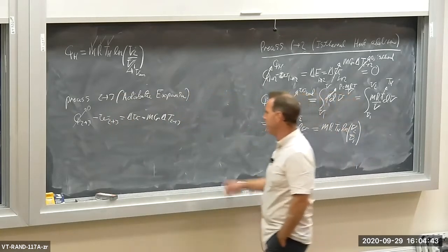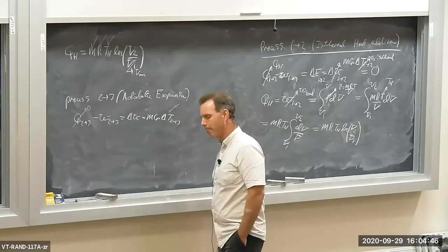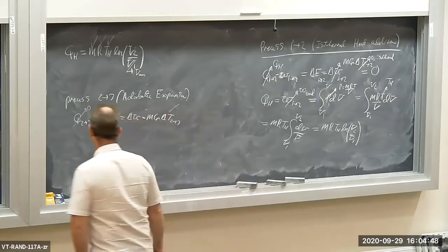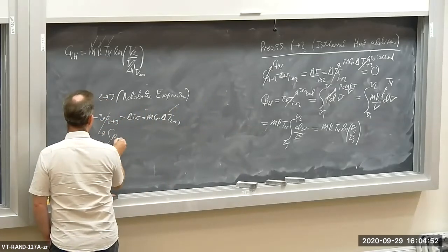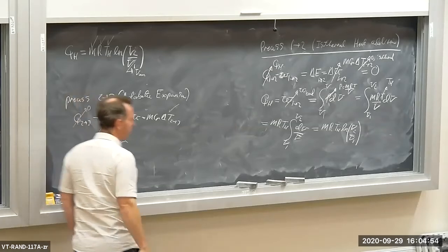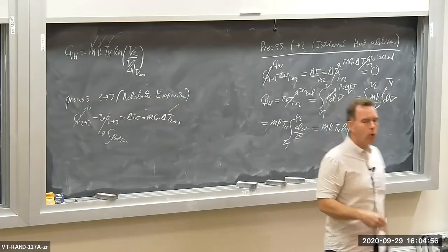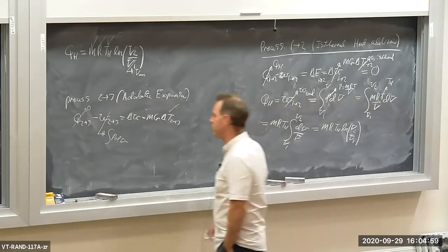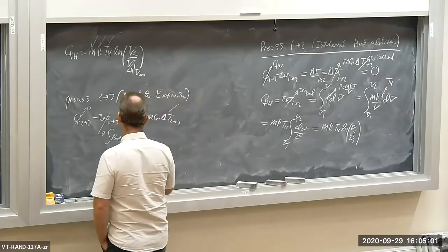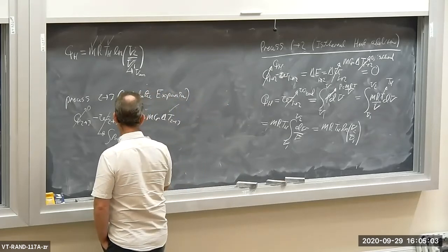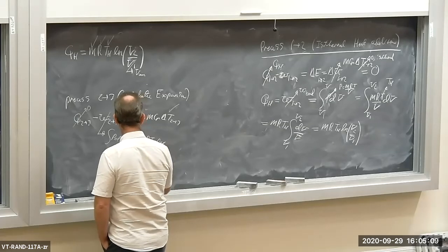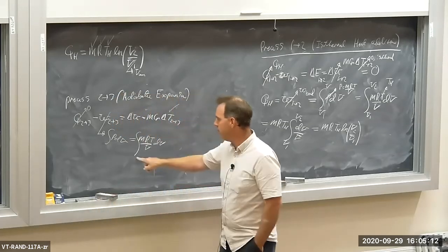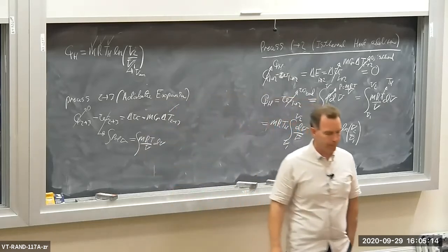I know what the temperature difference, delta T, is. And I know that the work is boundary work. So this is equal to the integral of PdV. And of course, pressure is a function of, according to the ideal gas law, a bunch of stuff. I'll have an integral of mRT over V dV from V2 to V3, okay?